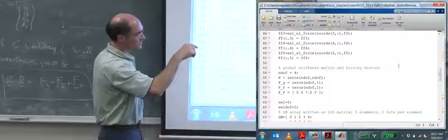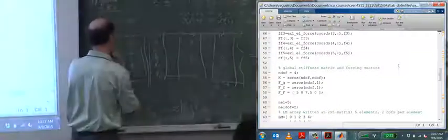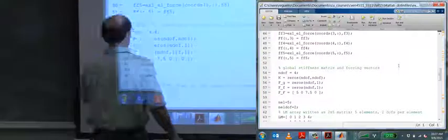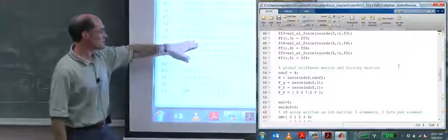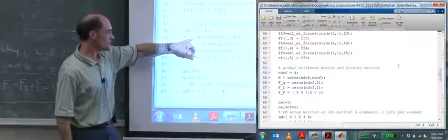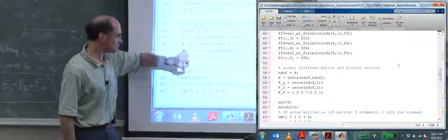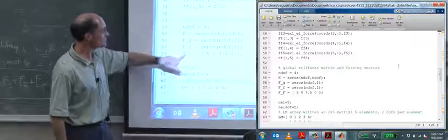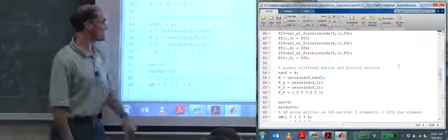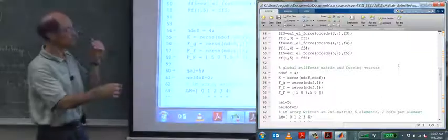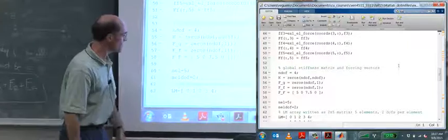You'll see in a moment that the D1 and the D6, we don't actually typically store those as D1, D6 in a code. So here we go. We initialize again. This will initialize to a 4x4 matrix. Our FG will also be assembled. F sub F will be assembled. For capital F, we're just going to discretely put in the numbers: 5, 0, 7.50. We know what nodes the concentrated forces are. So here's where we do the assembly. The whole point of this is to get to the next part of this code.